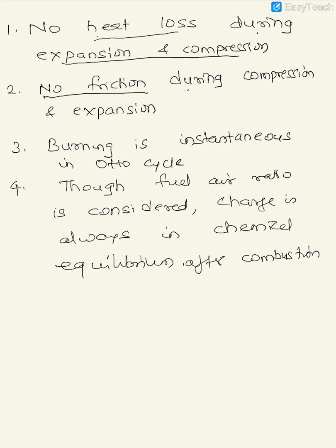In the real engines, especially in the petrol engine, we are assuming, in the Otto cycle analysis, that the phenomenon of combustion, heat addition, is instantaneous and it is at constant volume. In reality, the phenomenon of combustion is not instantaneous. But in the fuel air analysis, as also in the air standard analysis, we assume that the burning is instantaneous. So we continue with this assumption in the fuel air analysis.